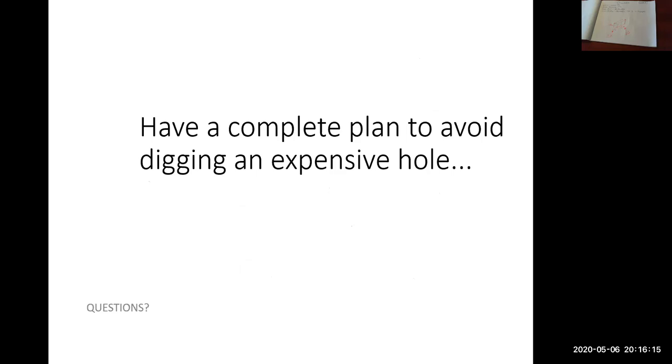So have a complete plan to avoid digging an expensive hole. So some things that I still do as an estimator, I've been doing this for 20 years, over 20 actually, sketching things on your drawings. So sketch out your proposed excavation on the drawing. So for instance, our oil interceptor, you could sketch out where and draw it to scale.